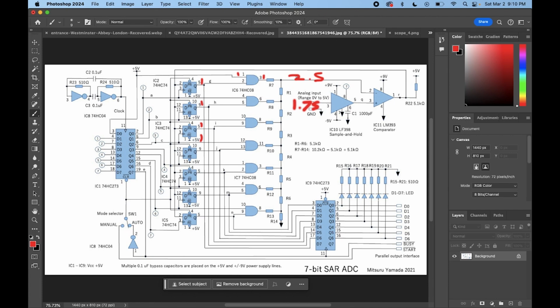So we'll get, which will generate a 0 here. So we'll get a 0. And then this takes us to the next clock cycle. So let's go to the next clock cycle, and with this 0, we now have a 0 on the data, and then we have a 1 that's generated because this shift register shifts a 1 through from this V+, and it goes through from Q0 on 1 to then 2 on the next cycle to then 3, then 4. So let's go and see what that affects.